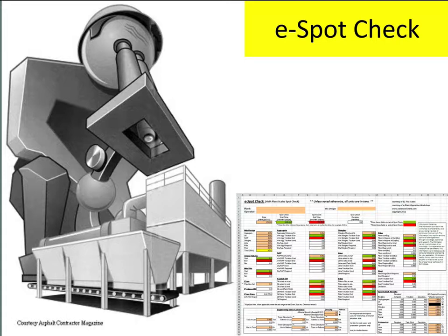When possible, volumetric measurements, tank stick, are compared to the gravimetric measurements. All gravimetric measuring instruments, such as scales and temperature-compensated meter totalizers, are compared to each other. A flag in the operator's mind should go up whenever a measurement deviates significantly from its set point. The eSpotCheck spreadsheet has yellow flags going up in case the operator's mind flag has not been completely raised.